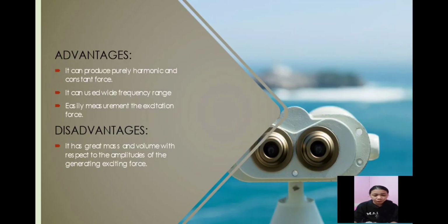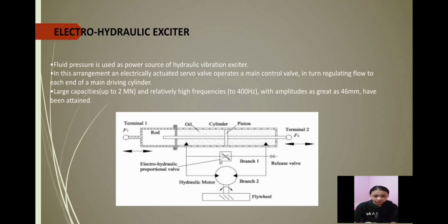Advantage: it can produce purely harmonic and constant force. It can be used over a wide frequency range, and the excitation force is easily measured. Disadvantage: it has a great mass and volume with respect to the amplitude of the generated exciting force.